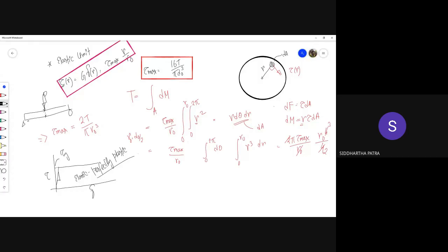Of course, the stress is maximum at the circumference in the cross section once you have a given cross section. But that was true for bending as well. That in a given cross section, plasticity or yielding would start from the outer layer. I'm not talking about a particular cross section. I'm talking about where in the geometry. Is there a particular cross section where the yielding starts first?